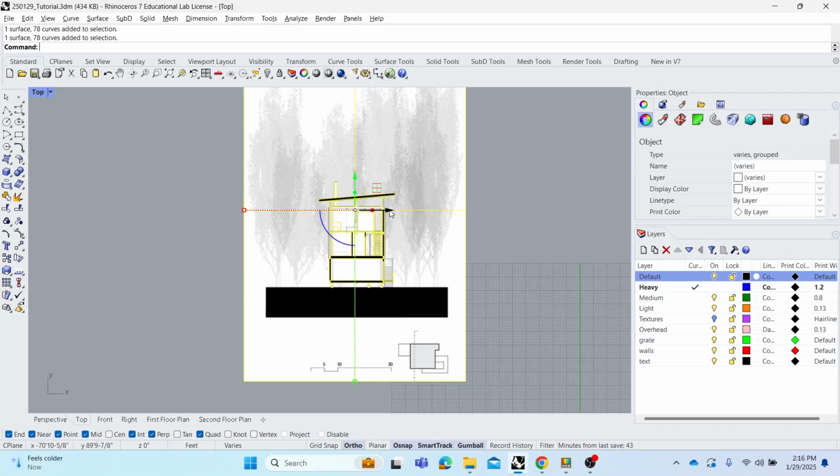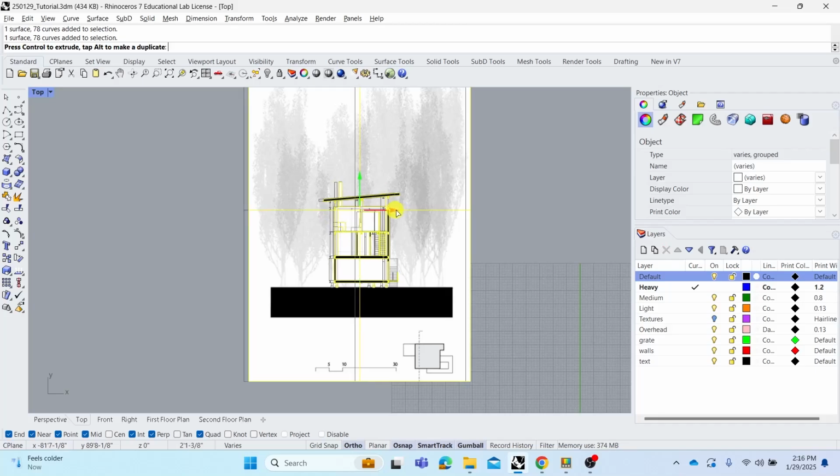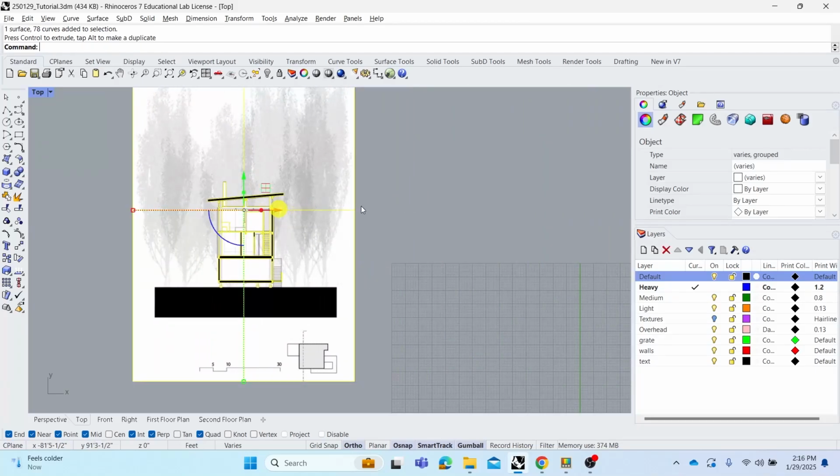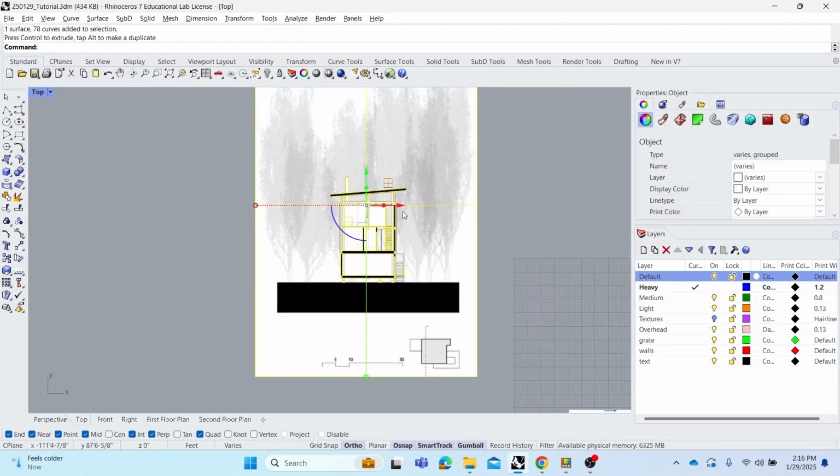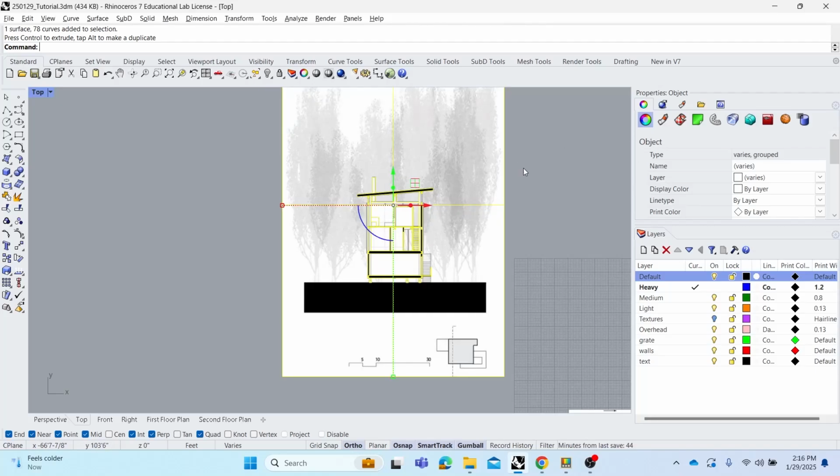The arrows, that's the shortcut for move. You can drag them and it will move the element however much you drag it, or you can just touch it, like click it, and you can specify the distance that you want them to be moved, such as like 10 feet, right? It moved it 10 feet over. That's the same for every arrow.